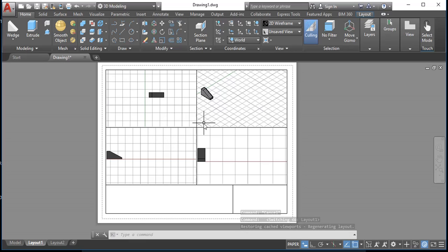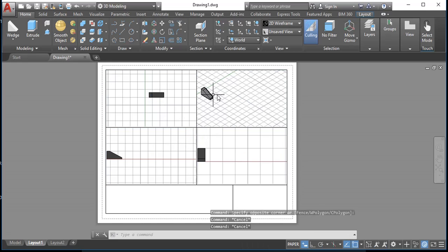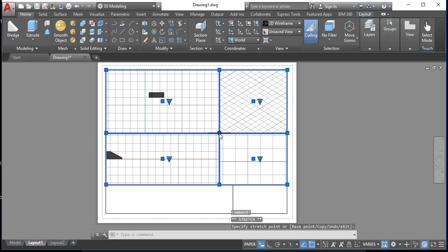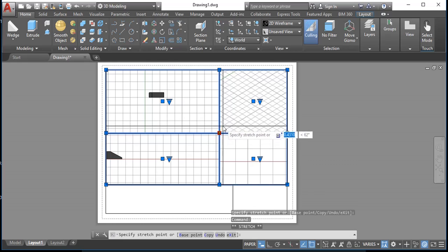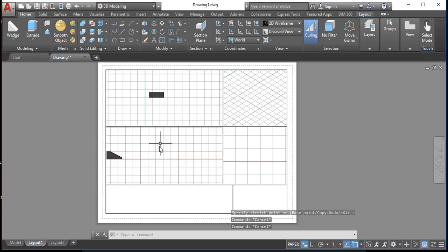It's at this point that we're going to have to tweak this around just a little bit for your drawing. So I'm going to scoot over these viewports, and then I'm going to scale them to make sure that they print out full scale. So I can select all these 4 at once, and I can grab this corner and drag it over a little bit. And I can actually change all 4 viewports at once. It moves them all automatically.